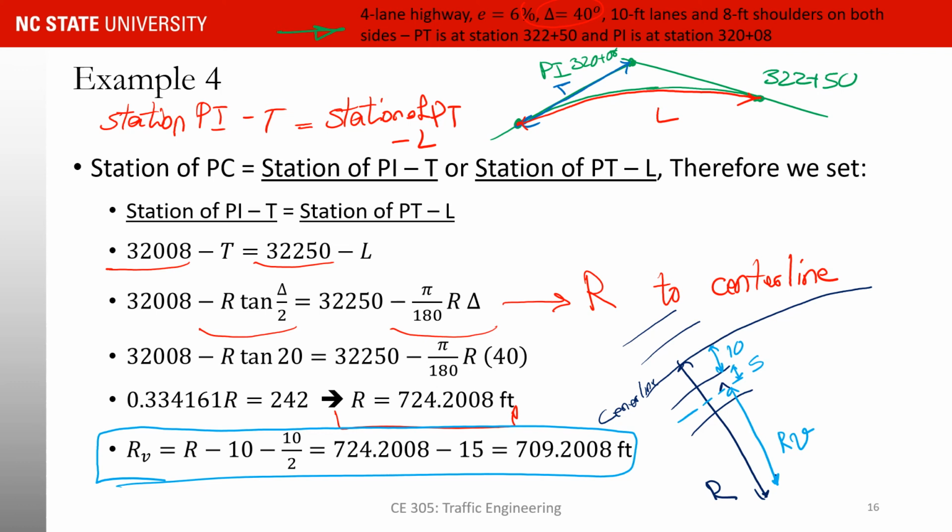So what is going to be the speed that you're going to use on that curve? It's not going to be 50. It's not going to be 45 or 40. It's going to be 35. Because if you go more than 35, you're not going to have enough time to stop your vehicle if you see something that's stopped on the curve. Now let's take a look.